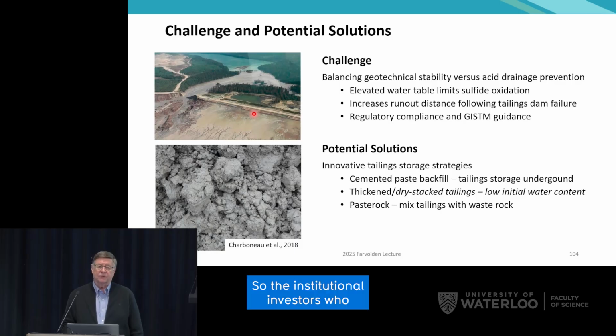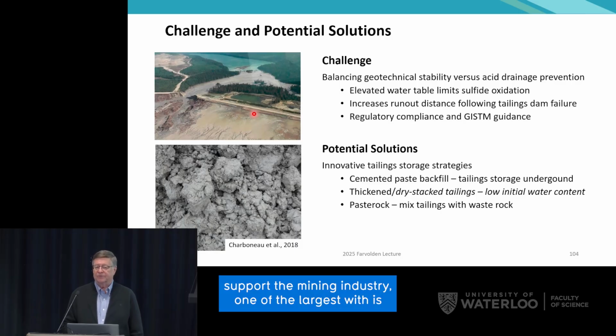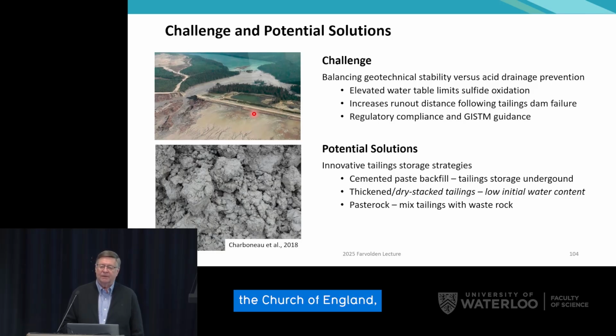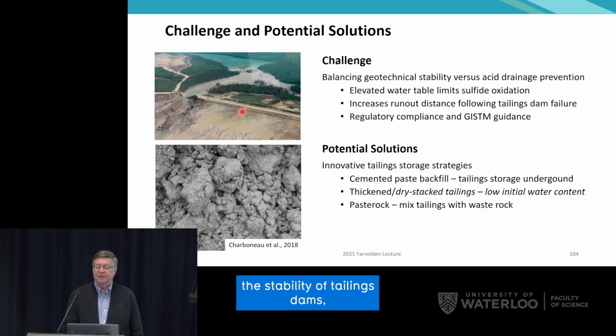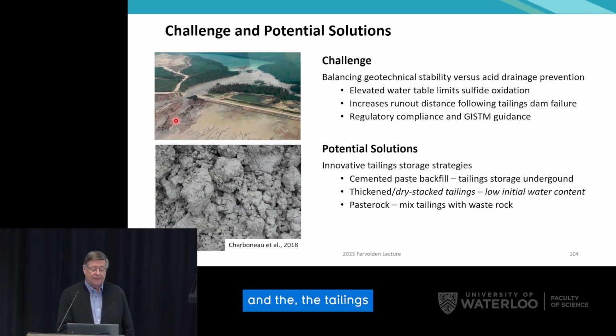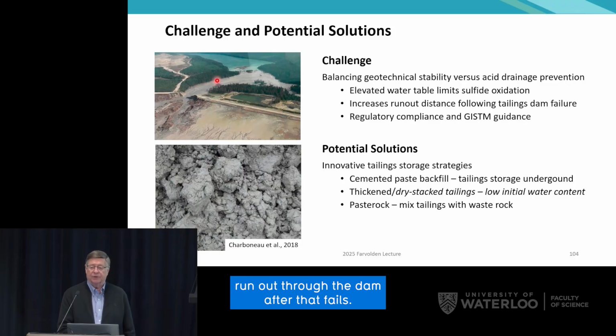So the institutional investors who support the mining industry, one of the largest of which is the Church of England, got together and decided this wasn't something they would tolerate anymore. So there's been a real focus on maintaining the stability of tailings dams and enhancing their structures. Most of these failures were due to foundational failures, not failures within the tailings dam itself. So the foundation fails, and the tailings run out through the dam after it fails.